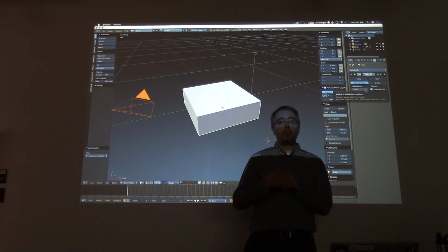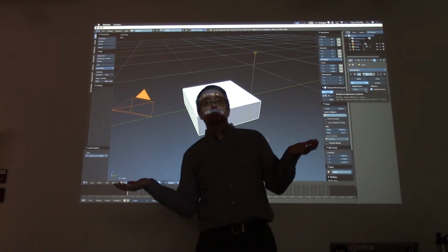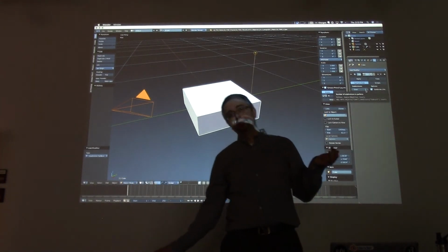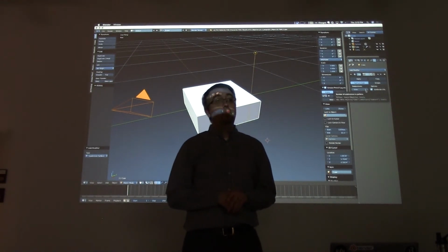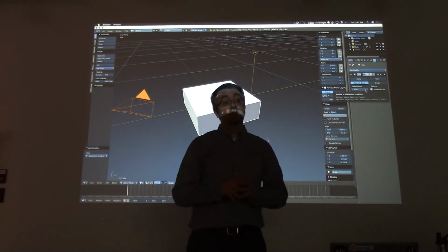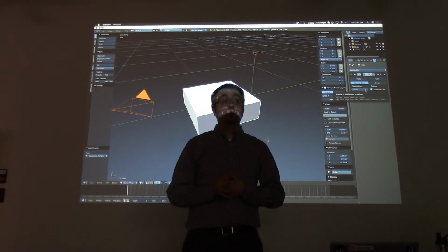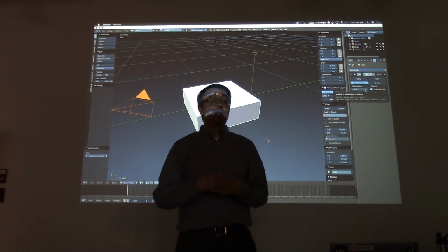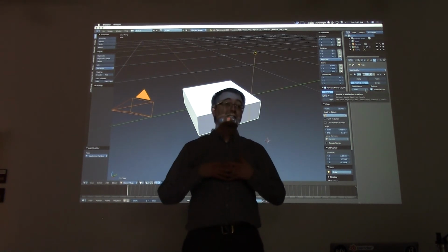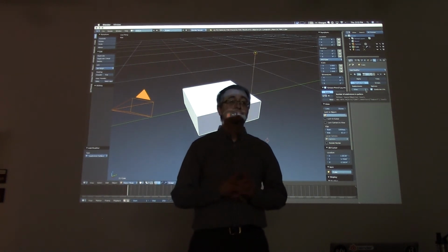Because remember, render doesn't matter, because we're not rendering. Then why don't we just put it to 0? Well, because 0 would mean no extra subdivisions, but we actually want more. Oh, you mean render? Yeah, unless we hit the render button, it never even looks at that setting.